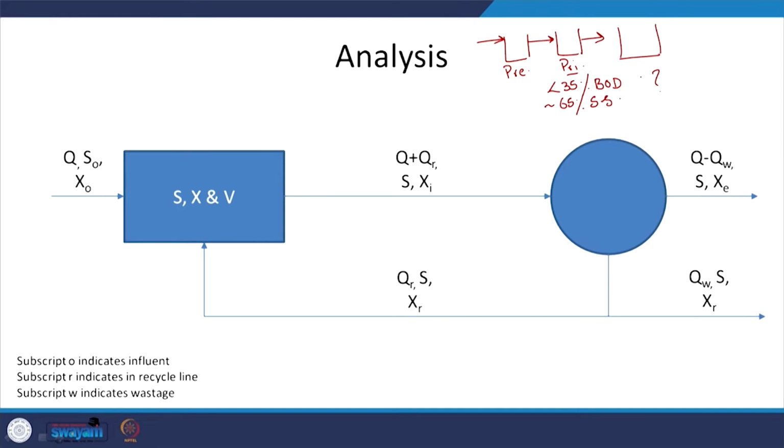As mentioned, we are going to use microbes and we are going to provide oxygen, so that the microbes use their enzymes to catalyze this degradation of our waste, or their food, right, and you are going to improve the kinetics. Again, we saw that microbes use the compounds, or our waste, for two processes. One is for energy generation, one is for cell synthesis, and the electron acceptor in the overall reaction, if I may say so, is oxygen, let us say.